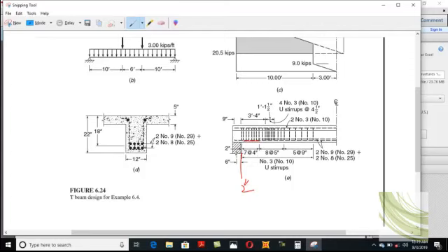This much. Okay. Then they select 8 stirrups at a rate of 5 inches center to center. And then they select 5 stirrups at a rate of 9 inches center to center. Okay. Now, after that, no stirrups are required. So basically, you know that this 3 foot 4 inches, which is I think so, and this is used stirrups.